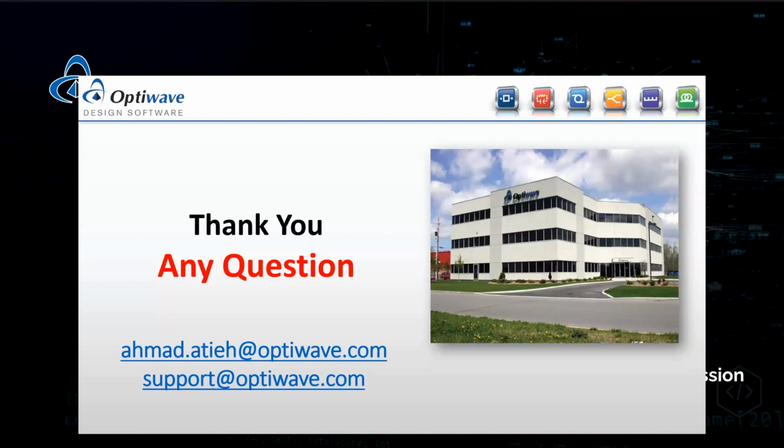We have the option to do the analysis on optical pulses which carry signals, and the power level can be different, so we don't know if a bit is 1 or 0. So we have added a threshold to decide on 1s and 0s. The other option is if the signal is binary coming directly into the component. In that scenario, we have to enable the binary option.